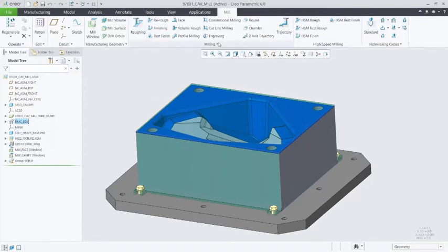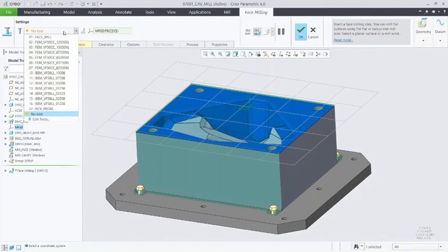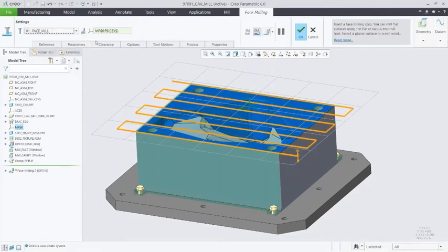And we see in our mill tab that we have special tools for all of our different types of milling, where that intelligence is built in. So it helps you create really effective toolpaths for each of these different types, because it knows what you're trying to do. So first we're going to look at our mill window, and we're going to add a toolpath by selecting a tool. Our mill window is the volume of space that we want our tool to work through.